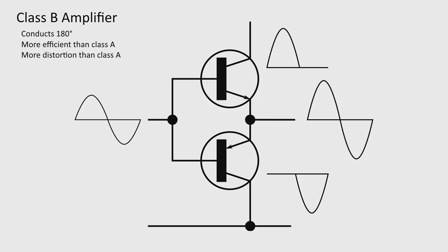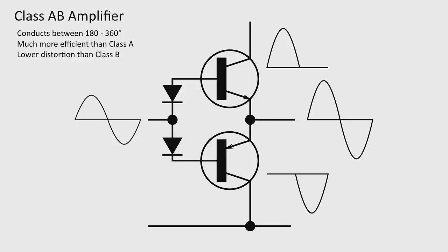There is another class that's very similar to that, Class AB. That means it's not quite as good as the Class A amplifier. It's not top of the class, but it's not a beast unit either. It's kind of floating in the middle there. It's like an A minus or a B plus. That's a push-pull design there. And you can see that top transistor in this circuit is only doing the top half of the waveform, the positive half. The other transistor is only doing the negative half. They are biasing these differently.